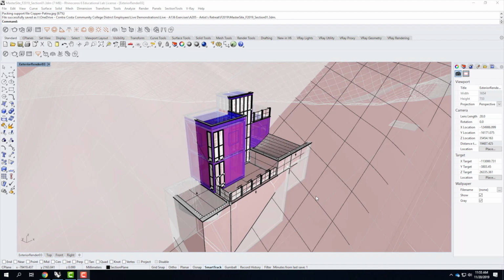You've seen this happen in SketchUp where the sun can just come in. That's not really a true reflection of what the building would look like inside, as if the rest of the building was there. So we're going to make this building a little bit special in that we're going to make the walls and some of the materials, the part of the building that we're clipping, so to speak, opaque to light, but transparent visually.